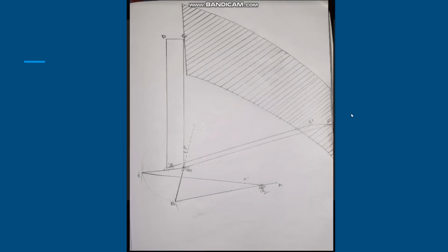To draw this configuration, we take the point O2 and draw the arcs O2B and O2B dash, and from the O4 point we draw the O4B arc and O4B dash arc, and we join the lengths to form the dead center configuration. The delta angle is also given. According to that, we draw the lengths which we require from our question. The shaded portion is the area wiped by the mechanism, where the extreme positions of the wiper are C and C dash.